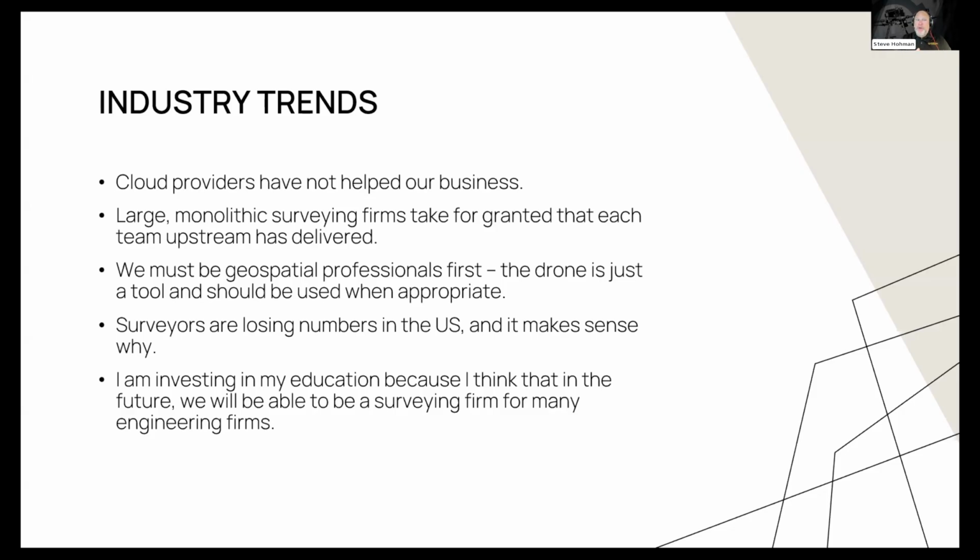That's awesome. But when I look at your contour map, and you've got what's clearly a pond with 5 different elevations on it, you haven't really delivered. What you've done is you've actually picked up vegetation. And the reason is because the person who's processing the data that you gathered doesn't know what's actually there. And so I see sloppy results because of that disconnect.